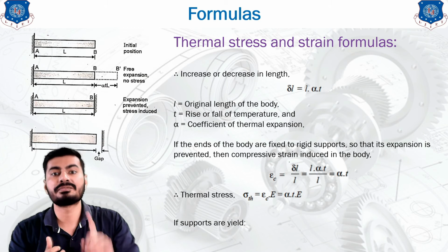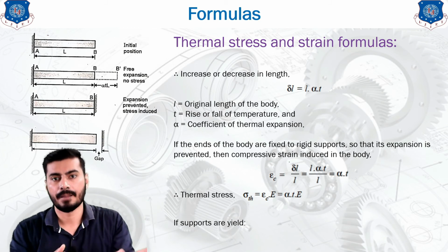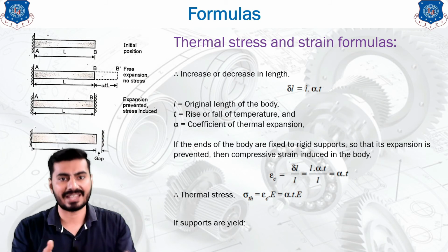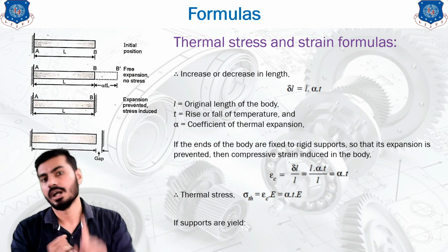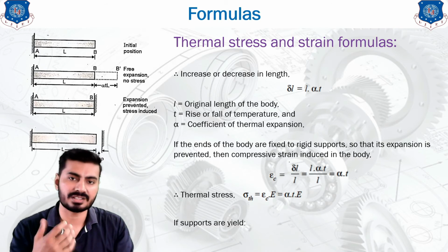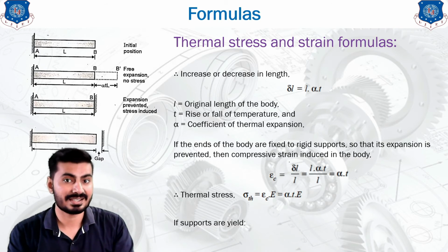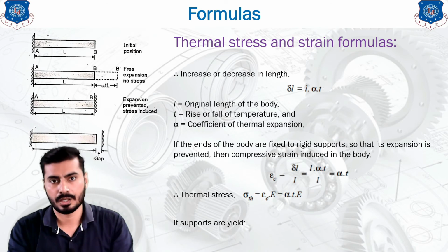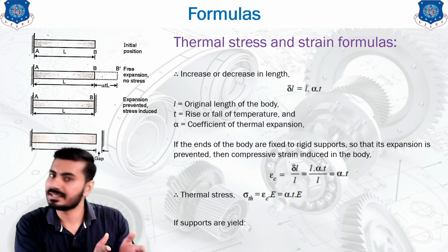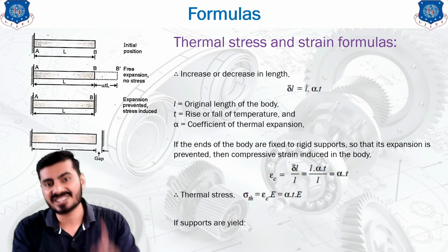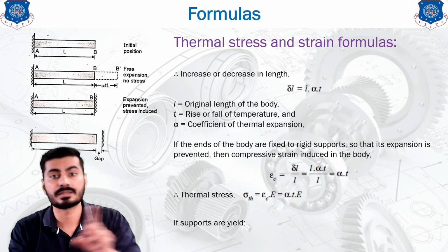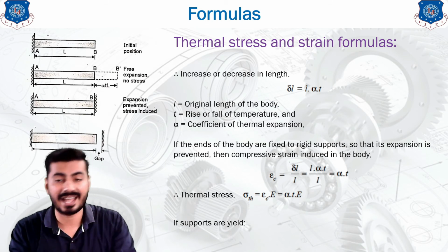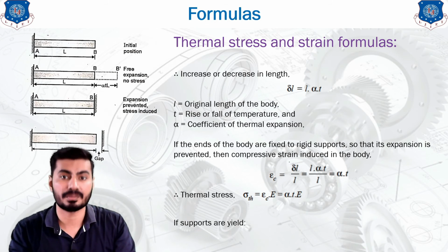Initially, the body was free to expand to fill the gap, but later on, after filling the gap, the body will face the resistance, and this resistance is the cause of the thermal stress. So the thermal stress will be generated after filling the gap. During the gap filling, there is no stress generated in the body, and that's why we have to subtract the deformation during the gap, because the deformation during the gap contributes very little or zero value in the thermal stress generation.